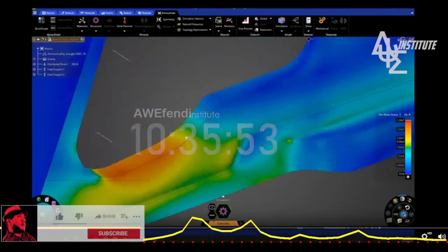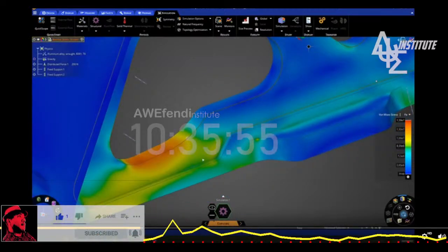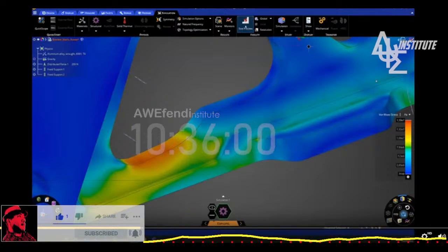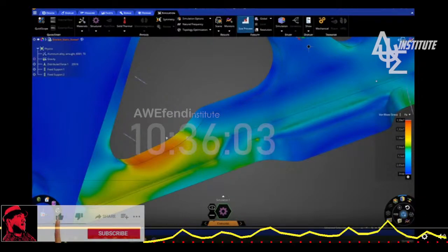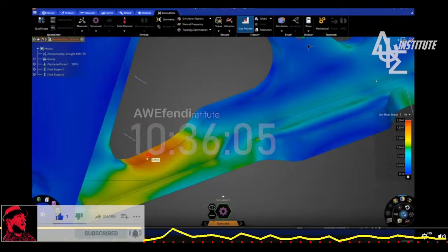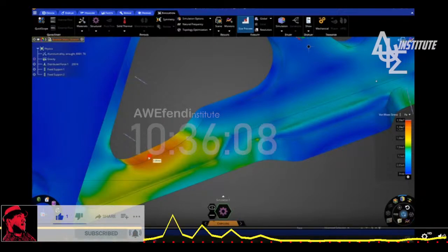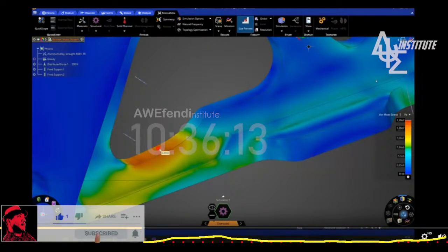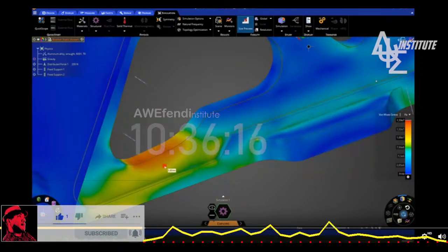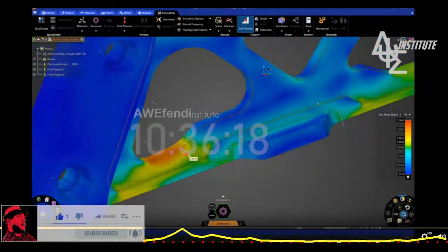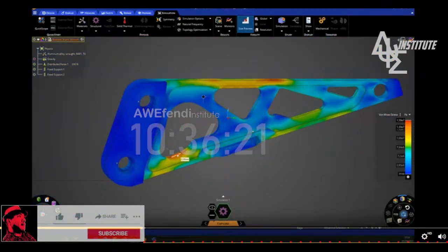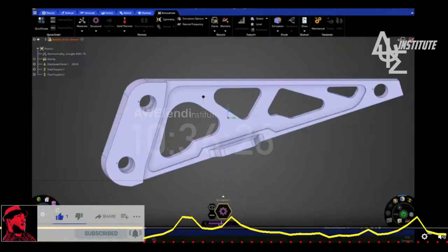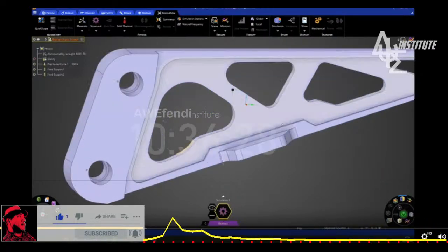Does the mesh have an influence? Because with the explore mode, you can't really visualize the mesh. What you can do is preview the size of the average mesh by clicking on this button. And when you hover over here, you can see, for example, it's using a mesh of 0.85 millimeters. But I would like to see the mesh itself and how the domain is divided, and if I need a finer mesh in that area. So for doing this, we use our refine mode. All I did was switch to the right over here, and you can see our refine mode.